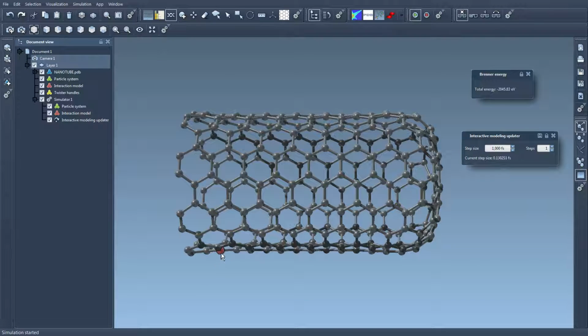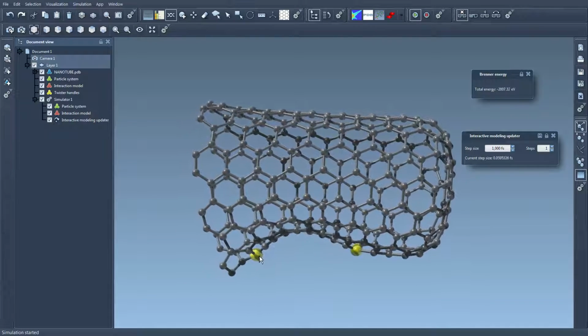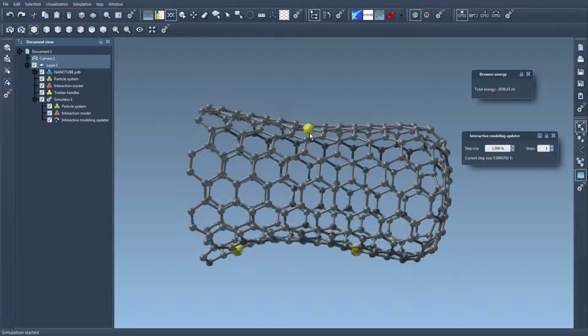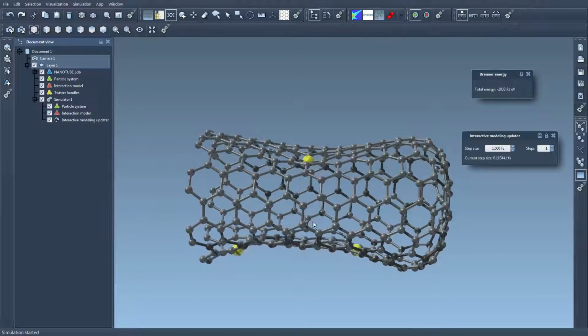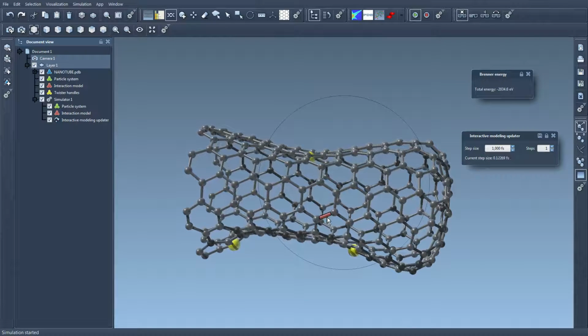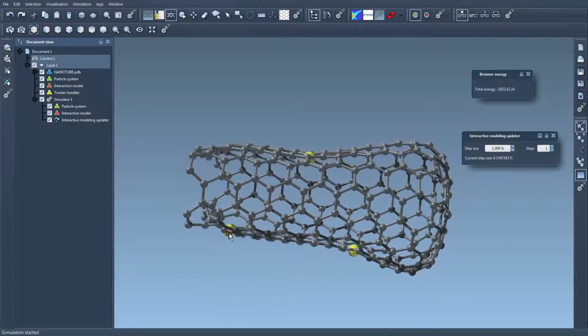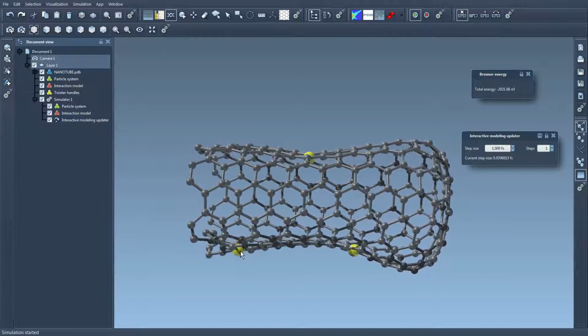But just a quick example, this editor allows me to add constraints. So I click on an atom and it lets me add a constraint, and I can then move this constraint to do more global deformations while constraining the positions of some atoms. So you see that several things are acting at the same time. One, the fact that the nanotube is being minimized, and the fact that this twister editor is helping me apply constraints on the nanotube.